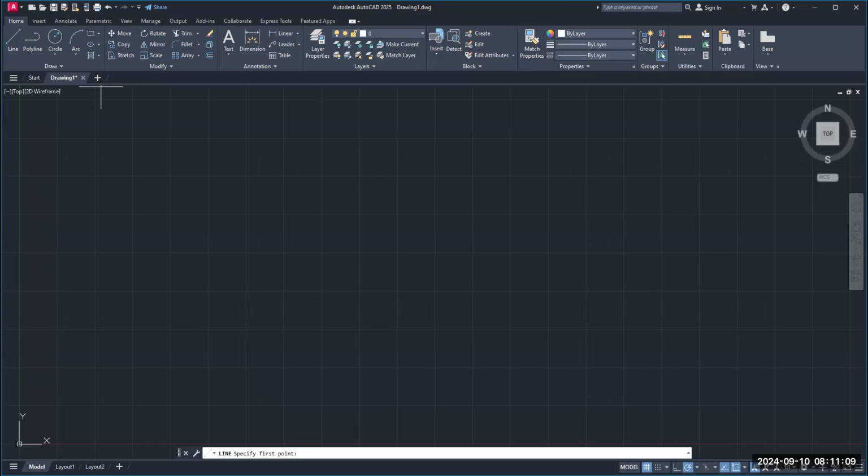And it's anchored, right? The line is anchored. I'll type in 5. Now it's already 0. Look, I don't have to hit the tab button here necessarily because my angle says it's 0 degrees. Now yours might not, so you might have to hit the tab button and put the angle in there. So I got 5 inches, 0 degrees, hit my enter button. I'm going to come down.